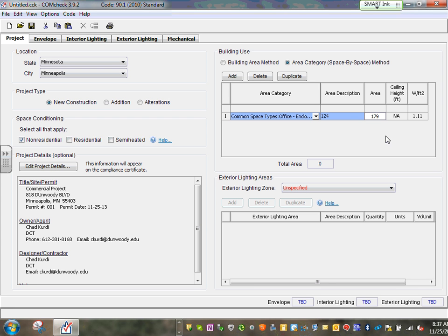I want to bring to your attention, guys: do you see what the allowance by the code for the closed office is, based on ASHRAE 90.1? They give you 1.11. You know what the code allows you to do? Three and a half, actually 3.5 volt-amps, which is very close to watts, versus 1. So 1/3 of what the code allows you to do. The NEC code book allows you to do 3 times more than what the energy code allows you. So you're going to be careful with that one. Okay, here's office number 1, gentlemen.